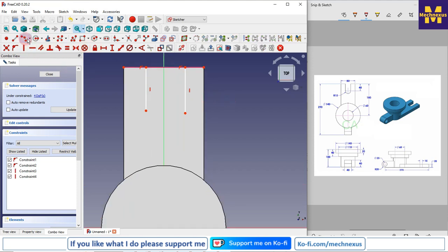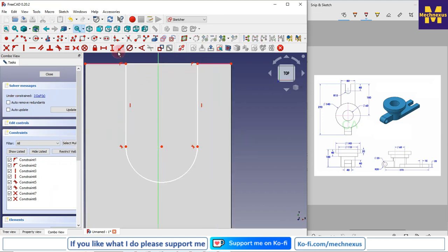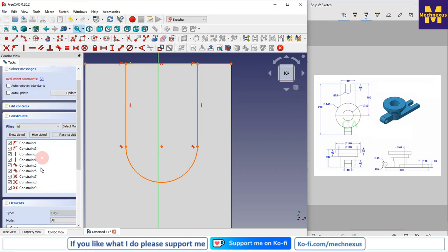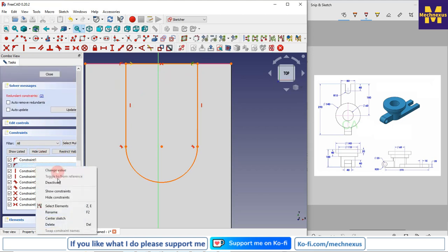Then I will click on the 3-point arc and make it tangent. I will also make this tangent, and I will join these 2 points, and I will remove this conflict. Okay, and now I will make it symmetric. Delete.